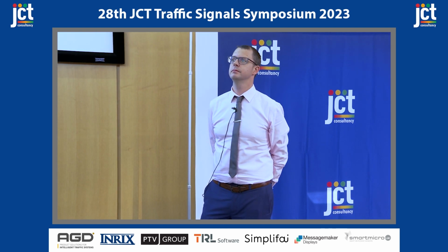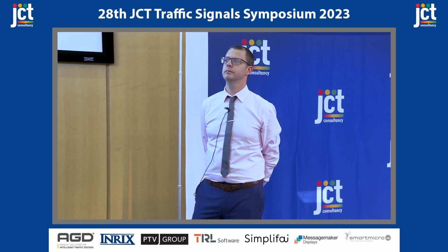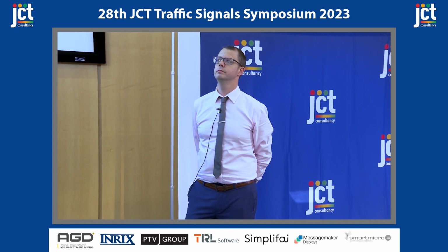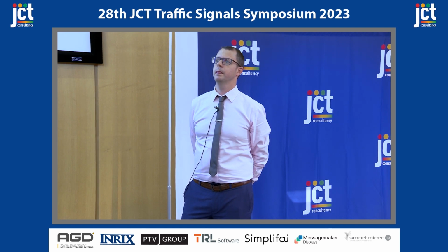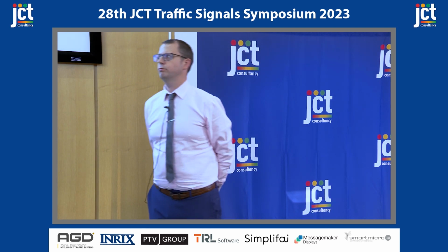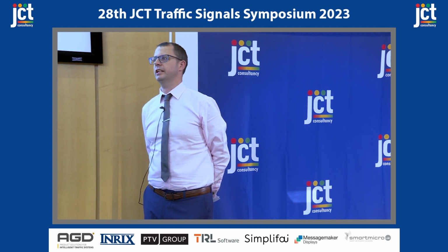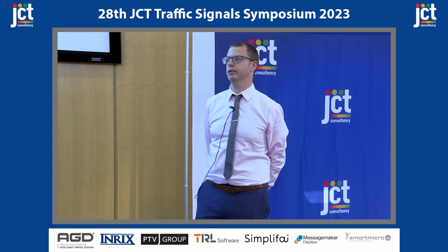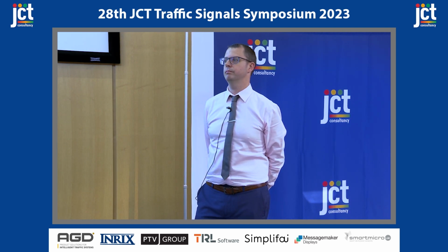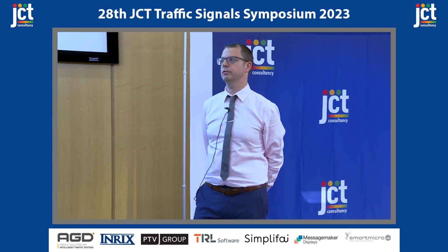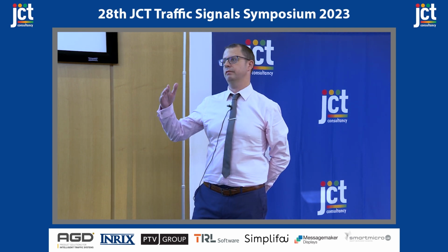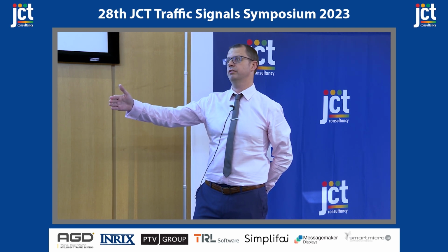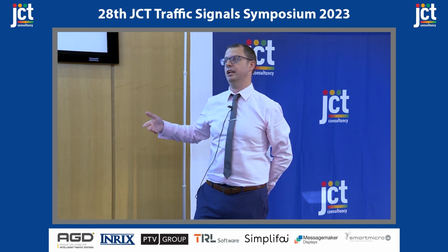You've also got two cycle phases very close together now on that design, on separate phases in the junction. Did you have any concern or mitigation for see-through issues, with people looking at the wrong signal head and taking the wrong action? There's no reason why the first stop line encountered by cyclists couldn't be moved back and you'd still achieve nearly everything that it was trying to achieve. The distance in a traditional cycle gate, the distance between the cycle stop line and the stop line after it, is only 7 metres. So it's actually a bigger distance in the layout I'm proposing.